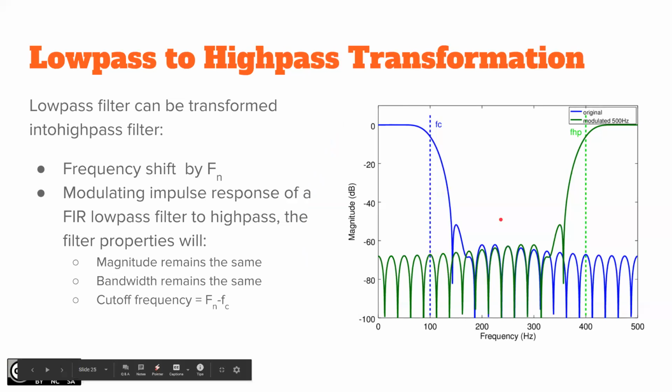there. So the low pass filter came out as a high pass filter, but remember that now the high pass filter cutoff frequency would be that Nyquist rate, fs over 2, minus the original cutoff frequency. Since, well, cutoff frequency is relative to 0 frequency, while the bandwidth is relative to the lowest and highest frequency on that band.